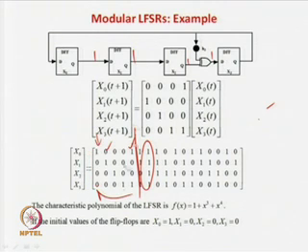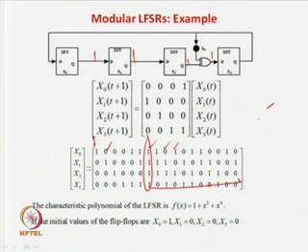But if your important test patterns are this one and this one, then obviously you will start from this seed vector and go forward from here, and you will not start from here. So what is the idea? The seed vector will tell you where to start from, and then what is the sequence of patterns. So we will try to give such seed vectors so that you can get the required test patterns, which you want to keep for testing, in the early sequence. That was the idea.